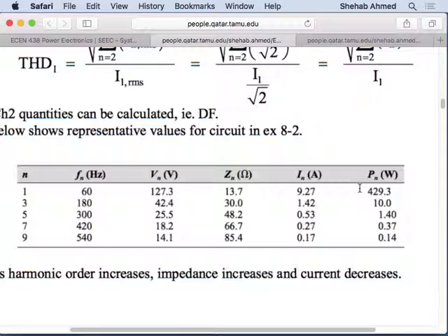If we do that, then all the components will be producing real power, because eventually we would like to create a voltage waveform that looks like a sine. If my voltage waveform looks like a sine and my current waveform does not look like a sine, I have a lot of power dissipation that's not contributing to real power. Here I have something that is contributing to power at the third and fifth and seventh. It's a little bit smaller, and the ninth as well, yeah.